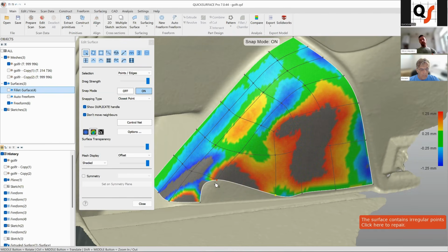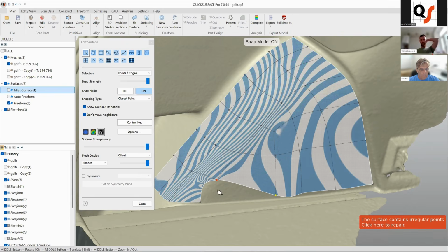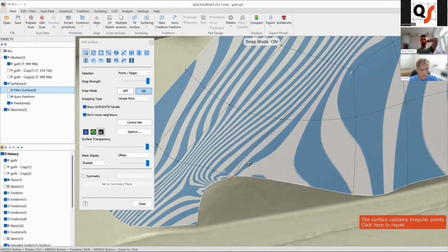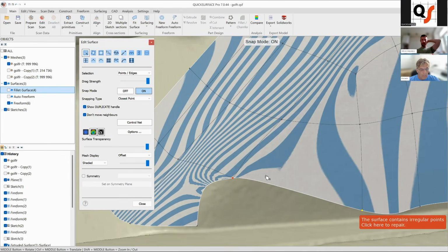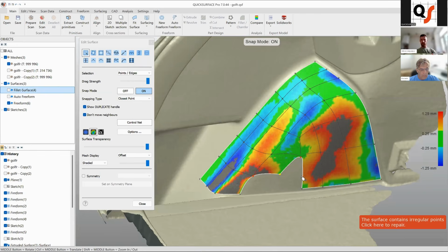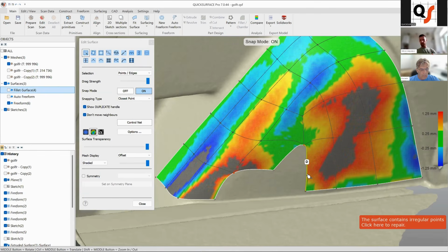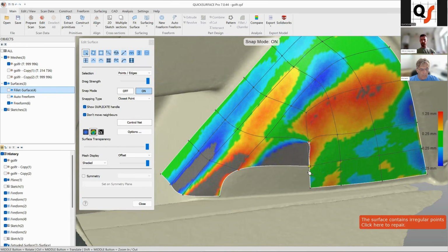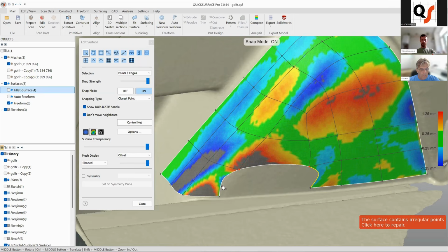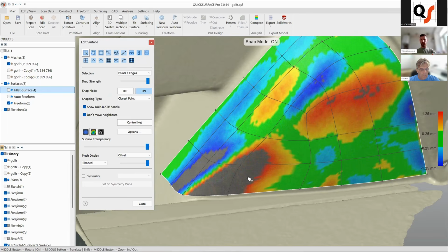which is not good because, for example, if you switch on zebra analysis, you can see that we have not really nice reflections here, so it's not smooth at this point. What we're going to do, we're going to split this one once again. So we have one extra row of quads connected there. And we can select these two and click bridge edges.